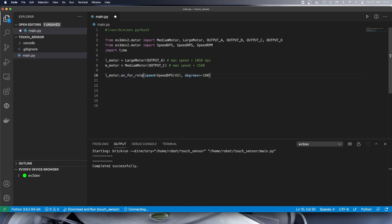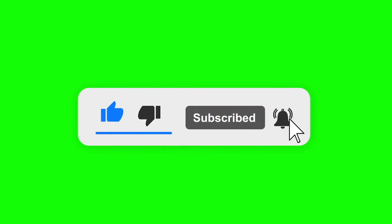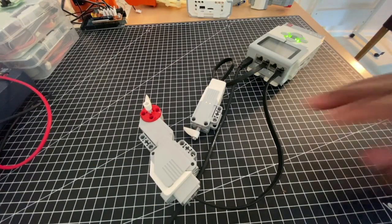So I'm going to make this rotations. We maintain the speed and we specify the rotations that you want it to make. So I will say rotations is equal to, let's say, 1, and I want it to do that at 50% of its maximum rated speed. So let's go to the workbench and see what this code is going to produce.